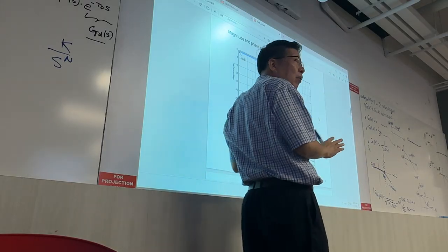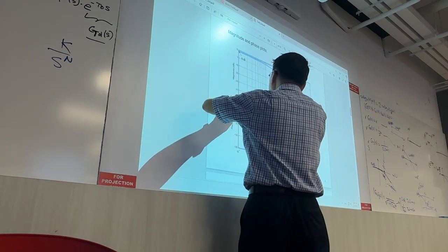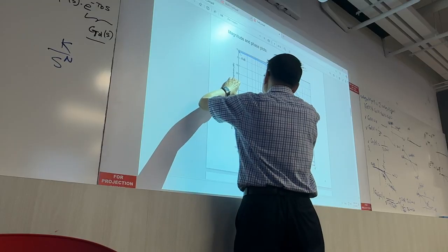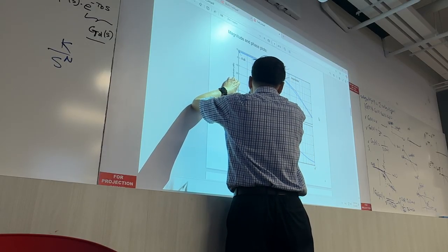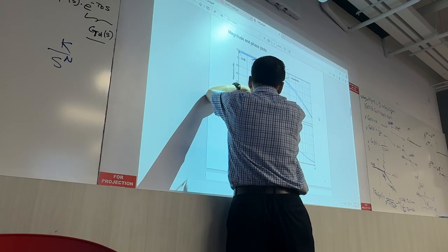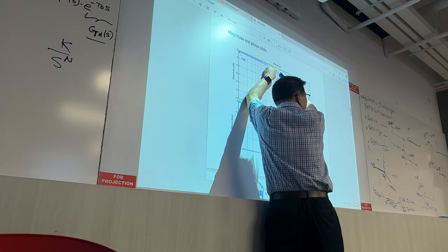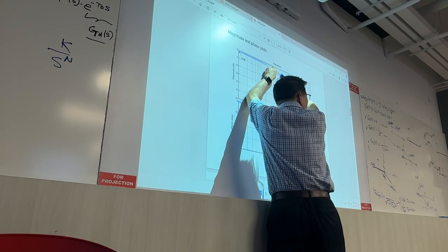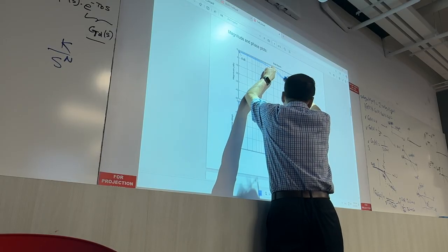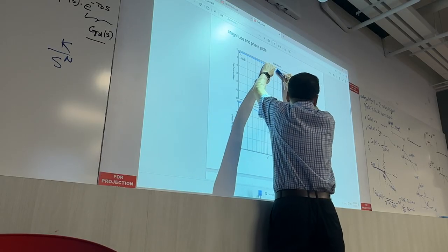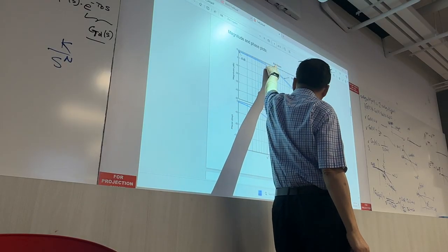Okay, it's very complicated, very easy to make a mistake. So the good way is you have 1 decade, and here you have 20 decibel. Then you draw a line, you use this one as a reference, and then you shift this in parallel, and then connect to this point. So this line will have minus 20 dB per decade, or anywhere. You just shift this one up and connect with this point. Okay, it's a good way to do it.